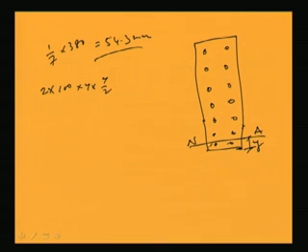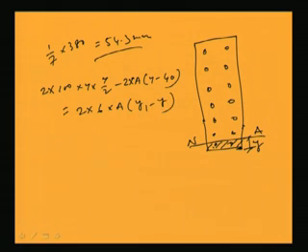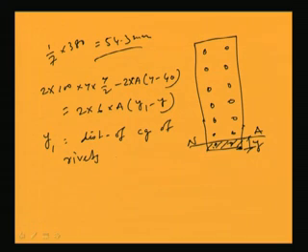This is this portion, minus 2 into a into y minus 40, because of the 2 rivets lying here, that should be equal to 2 into the rest 6 rivets into area of rivet into y1 minus y, where y1 is equal to the distance of the CG of rivets above the neutral axis from the bottom.